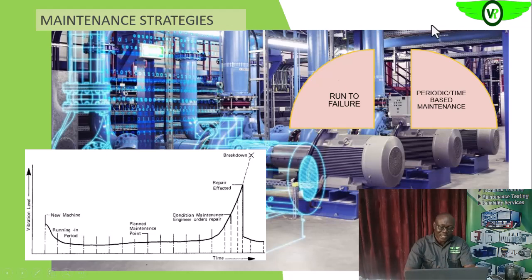So as it moves into the wear out region, we would have seen it, and then recommend maintenance before it goes into the failure region, irrespective of whether this is before the normal PM period or even after the normal PM period. What I'm trying to say is this: at the normal PM interval, we do our condition monitoring and analysis.